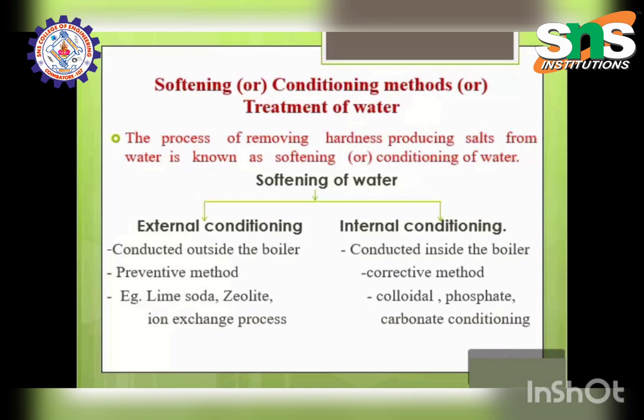In the cation exchanger, the resins containing acid functional groups like COOH or sulfonic acid are capable of exchanging their H plus ions with other cations of hard water. Cation exchange resin is represented as RH2, a common term. Examples for cation exchangers are sulfonated coals and sulfonated polystyrene.